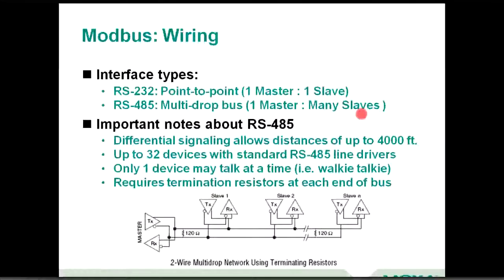Now, if you're not familiar with RS-485, it's an existing standard that basically defines the electrical characteristics on being able to share a single pair of wires that allows you to actually not only connect multiple devices, but actually do quite long distance with those. It uses differential signaling, which overcomes some different common mode types of noise that you can have on a network, and basically allows you to overcome that distance limitation you have with 232, which can be about 25 to 50 feet, and go lengths up to 4,000 feet with that.